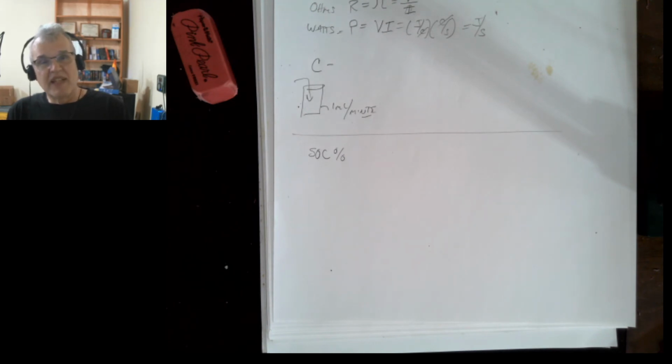Now you've got the capacity, the internal impedance, and the nominal voltage when it started. It's going to be charged up to 4.2 volts when you're done. Then you set the batteries aside for a month. After a month, you measure the open circuit voltage again. It should not have dropped below 4.1 volts. Really, for me, I use like 4.15 volts, even after a month's time. If it's dropped below that, especially below 4.1 volts after a month or so, then it's self-discharging, and you don't want to put that into your pack, because when you put it into your pack, it's really hard to get it back out again.